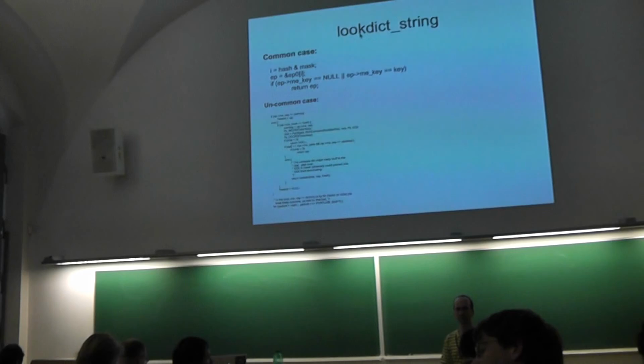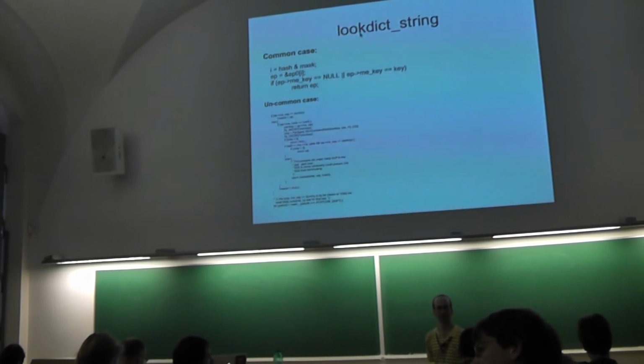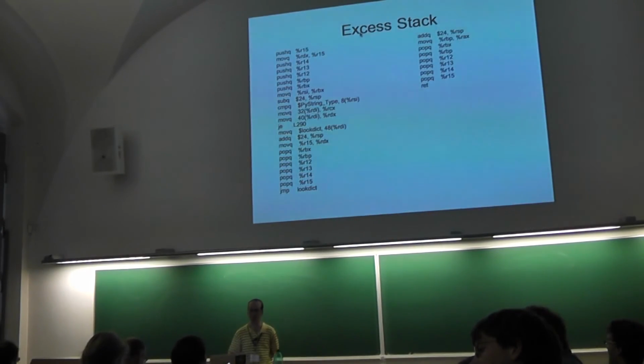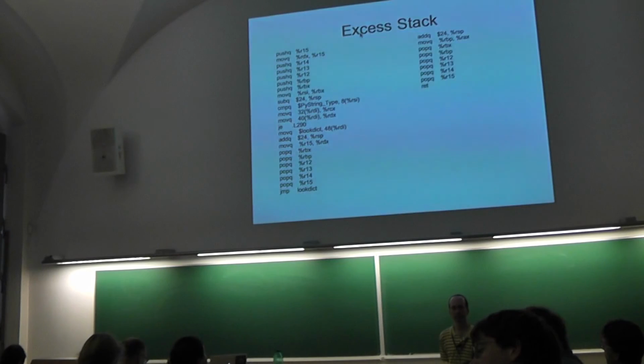Well, it's one of these things, damned if you do, damned if you don't. One of the things we see now is very small functions, where you do some of these stores, you do some more calls and then return. It'll stall waiting for the store queue because it has to do the stores, and then the loads have to wait for the stores to come back.